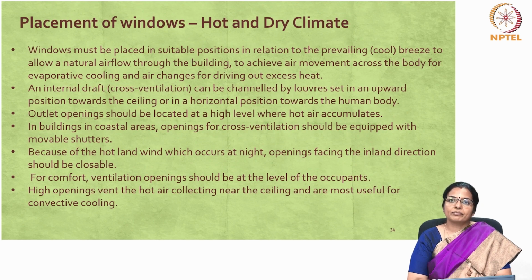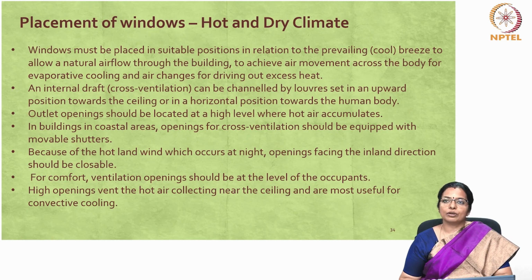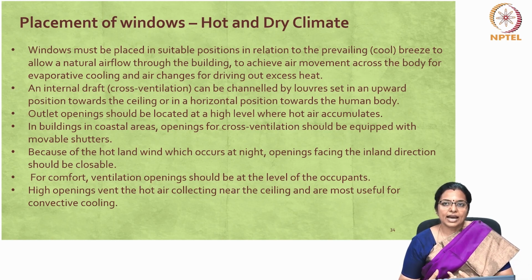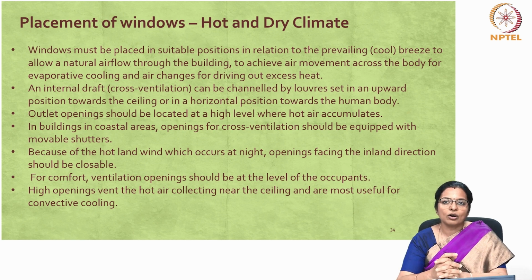Let us look at how windows should be placed. Windows should be placed in suitable positions in relation to the prevailing breeze, which should be cool, to allow a natural airflow to the building, to achieve air movement across the body for evaporative cooling, and air changes for driving out excess heat. An internal draft like cross ventilation can be channelized by louvers which are set in an upward position towards the ceiling or in a horizontal position towards the human body.